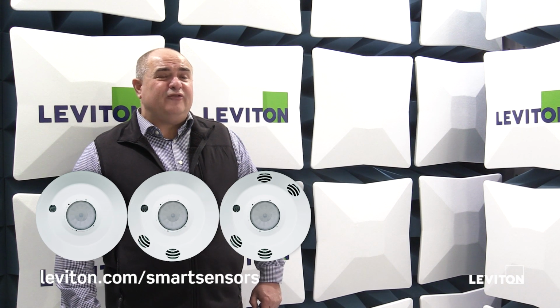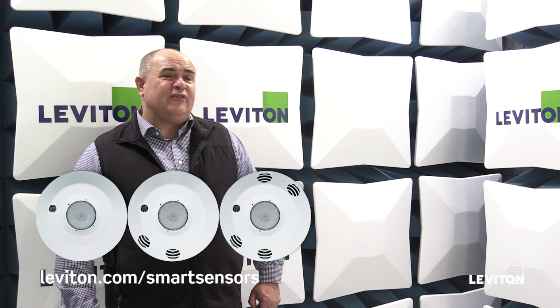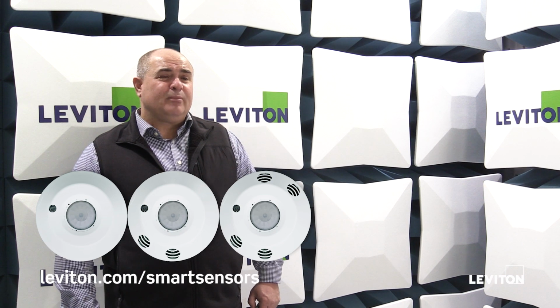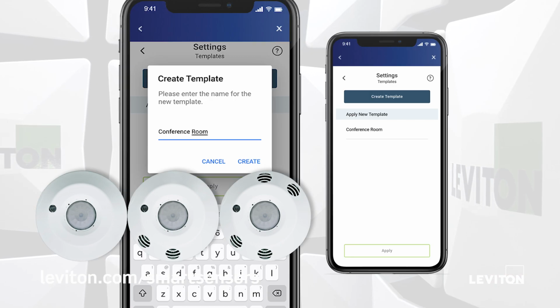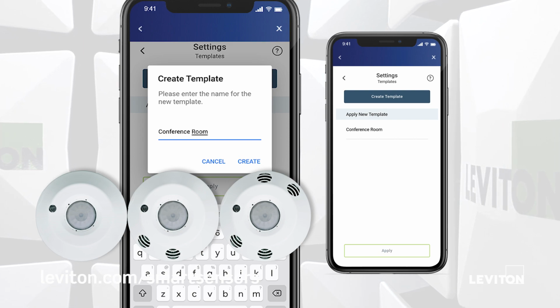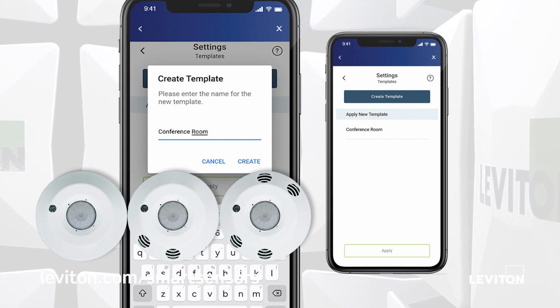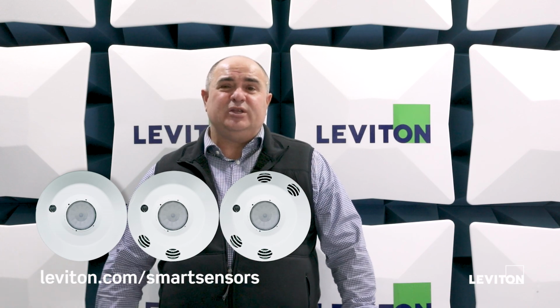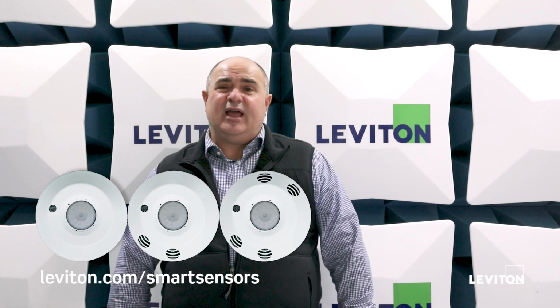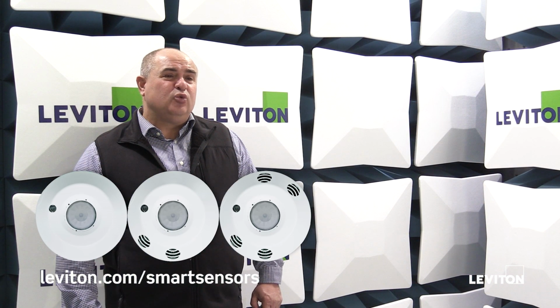And again, the other benefit is the grouping and networking of the individual devices. We can group up to 5 of these devices together to cover a much larger footprint than we can with the Wallbox sensor. And the last thing here, I don't want to minimize how important it is to have the ability to use custom templates. Once you've set up one of the rooms, simply by saving that template, you can go from room to room, and as we discussed, most projects have about 4, 5, 6 room types. You now have the ability to go into each of those room types and, in less than a minute, upload the settings into that.